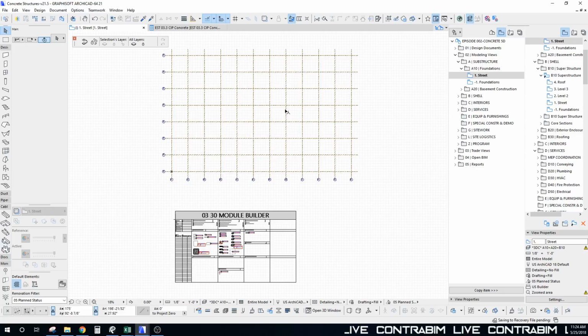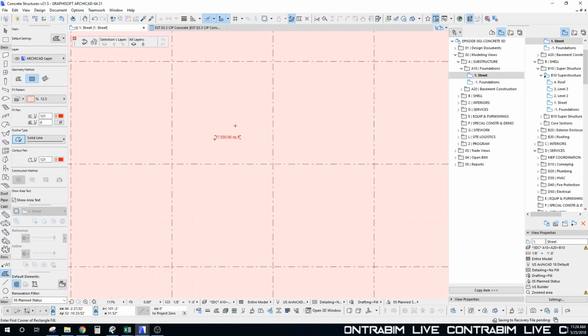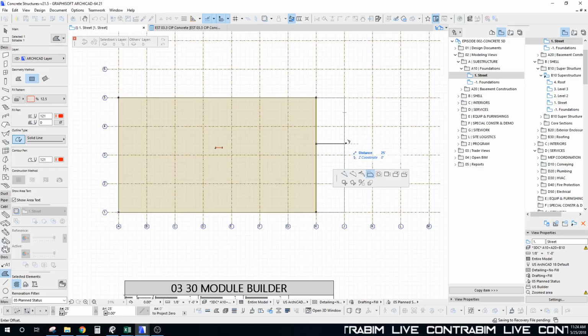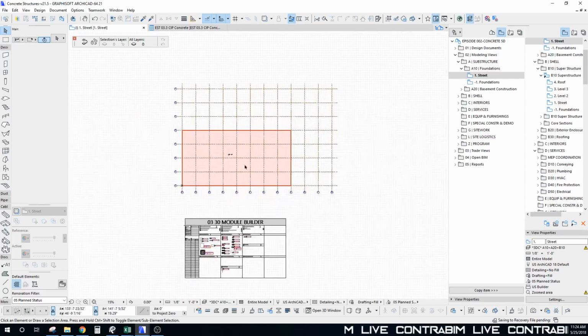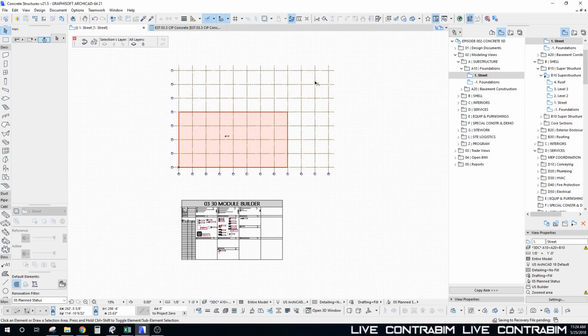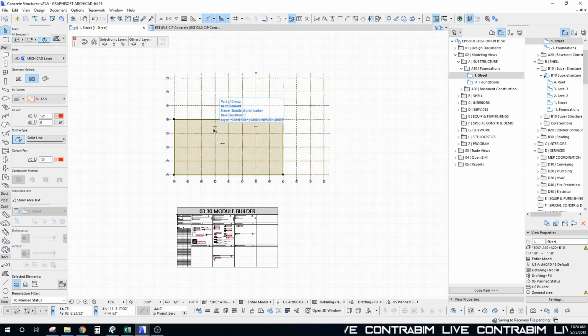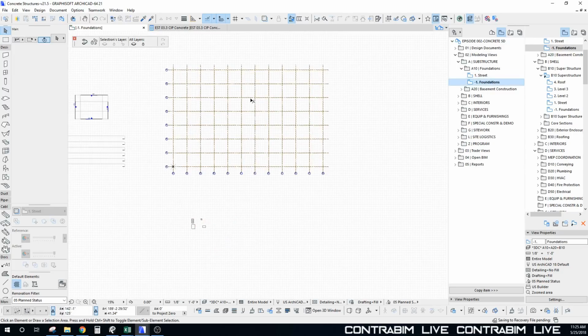So, okay, at this point, we're going to talk a little bit about what type of structure we're going to build, and where we're going to start is essentially I want to build just a tower, and that's what I'm highlighting right here. That's 17,500, and this tower is going to be coming out of a podium structure, which will be probably 4 or 5 stories. And so we're going to have a tower protruding from a podium structure. This is going to give us the chance to model a mat foundation underneath the tower. And then we'll just add in a few other footing types for some of the perimeter columns and shear walls that we're going to add.